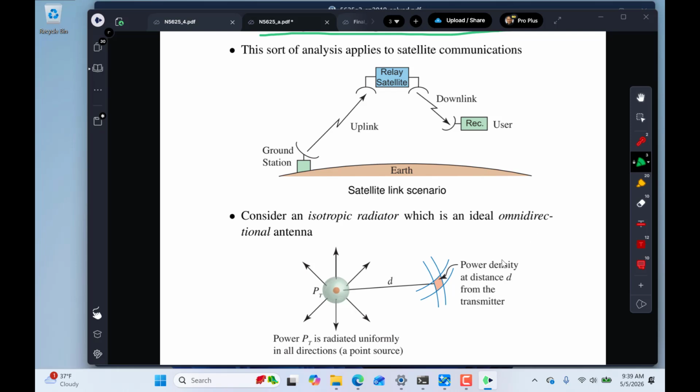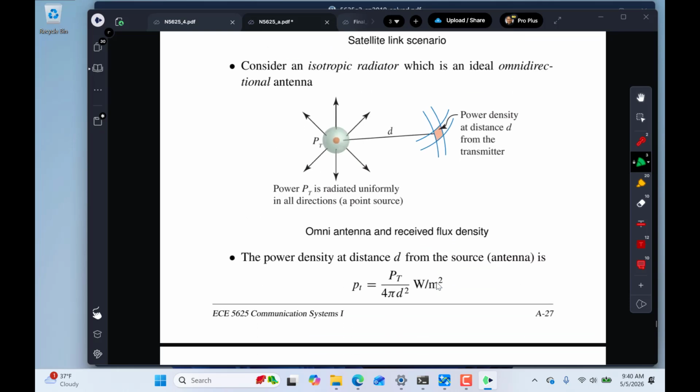So the key in this basic antenna modeling is we get a distance d from the point source, and we have power density, because the power that's driving the antenna element is so many watts, and it's painting it on the inside of a sphere of radius d, and it's going to paint so many watts per what? Meter squared, right? Because it's the flux density, watts per meter squared at some distance d, or flux density.